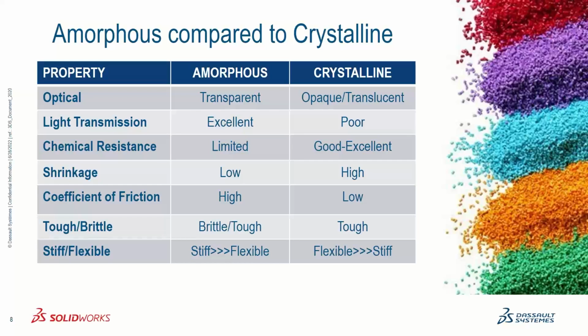Now, semi-crystalline materials have excellent strength and wear properties and good chemical resistance, but they typically lack in things like impact strength. Additionally, the degree of crystallinity can affect many characteristics of the polymer. There can be varying degrees of crystallinity among different types of semi-crystalline polymers, as well as variations within the same polymer, like polypropylene. Meaning no two polypropylenes are going to behave the same way. No two polypropylenes will have the same crystallinity structure, and therefore their shrinkage behavior is not going to be the same.